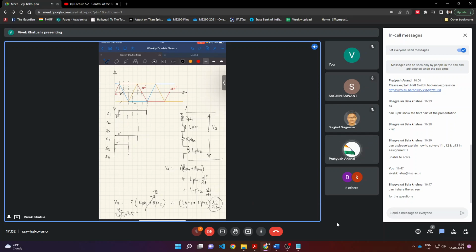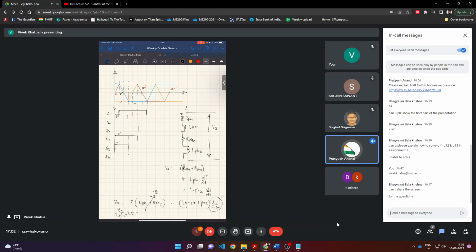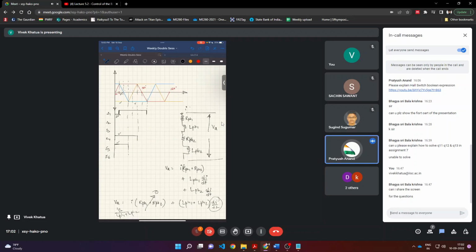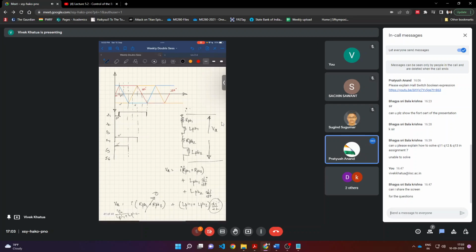Pratyush, you have something to say? Yeah. One question was there in this week's lecture. Sir has told that for BLDC we can't reverse the supply, like we did earlier, as that will short circuit. Here also we are using a diode, correct? In PMDC, for the H bridge we used a diode, and by changing the path we just reversed it. But how come we can't use that way for reversing this?